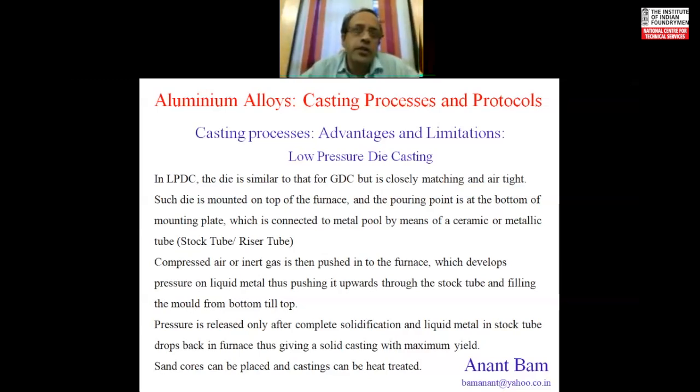And since the rim thickness is more or less uniform, it does not require any ring riser, and solidification is easily achieved, and productivity is increased, yield is increased. You can get as much as 90 to 95% yield for any alloy wheel.